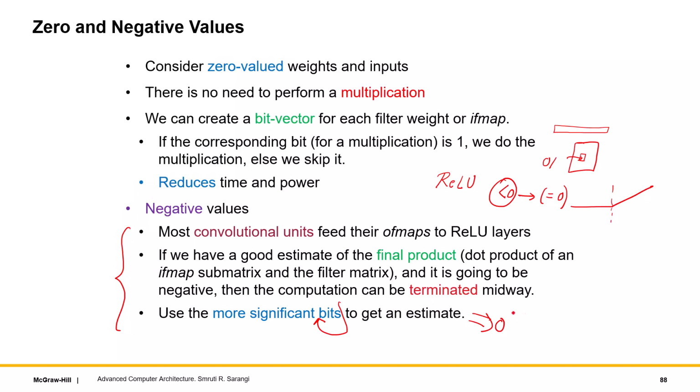If you recall, I had promised to explain what a binary CNN is. The main idea is that we have anyway decided not to use floating point or double precision in IF maps and filters. Let's say that a certain value can go from 2 to 5. We essentially quantize the range, and say we'll only consider 2.1, 2.2 like that, a fixed point. Of course, this is in decimal, but the same thing happens in binary.